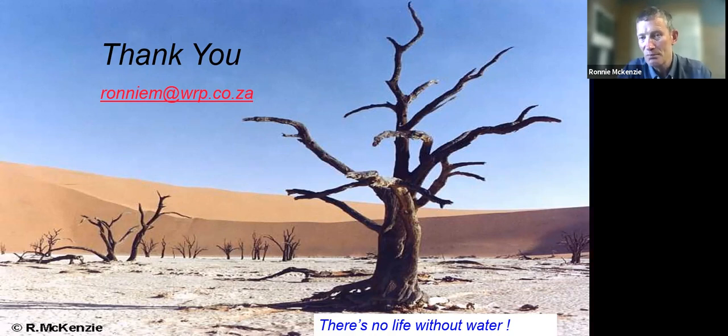And that was why on these big installations, as a former chairman of the IWA specialist group, I'm not recommending that we go to zones of 70,000 for pressure management. That would be pushing it a bit. Where it works well, we can still go in and do smaller zones. So I'm not suggesting that the UK is missing a trick by any means. That would not be my message there. Quite the opposite, I think. Going to smaller zones is probably a very good way to go where it makes financial sense.